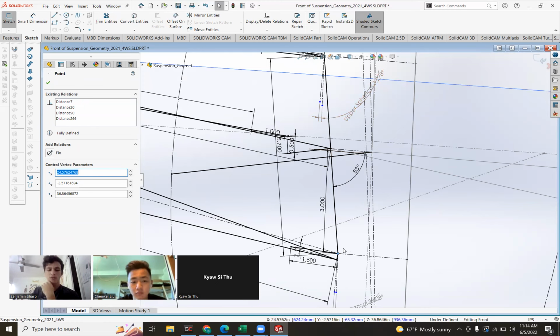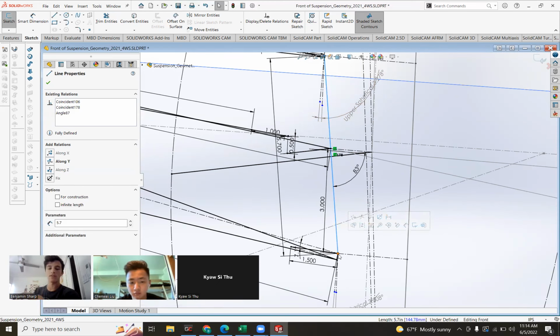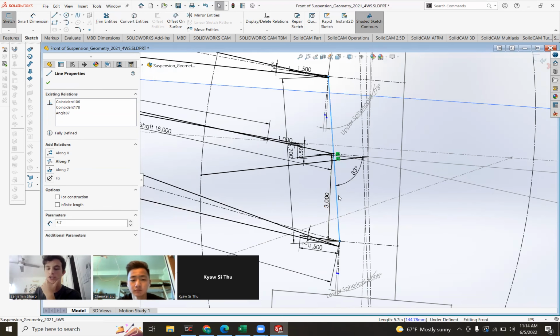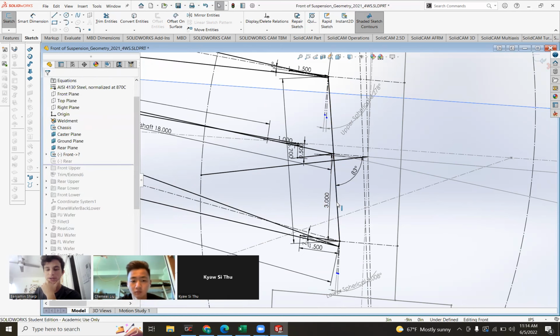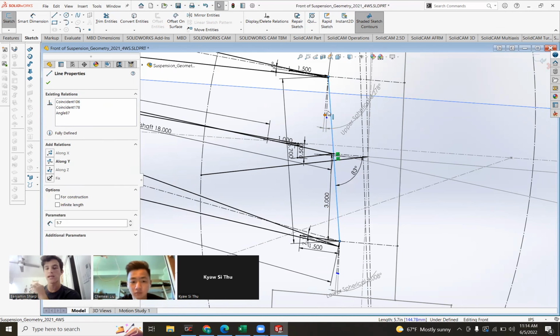And I think I told you guys once a while ago, but I'll just remind you again, the knuckle does not interface with the spherical bearing exactly. The spherical bearing just sits underneath it and on top of it, right? So the knuckle is actually a little bit shorter than the length of this line right here, but it's pretty close.